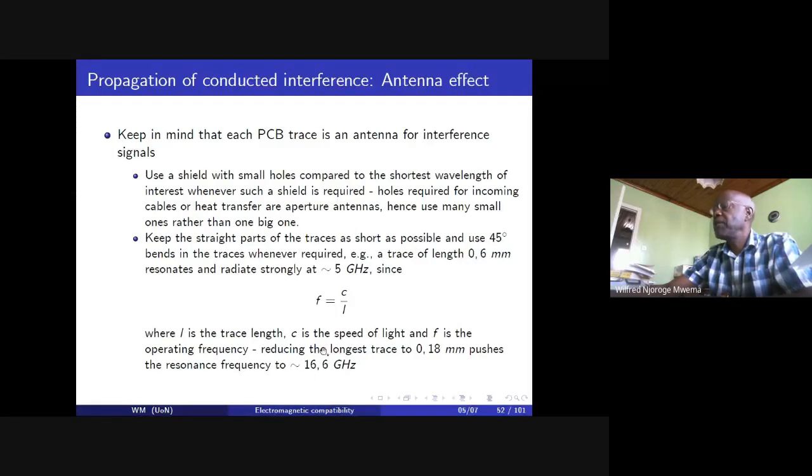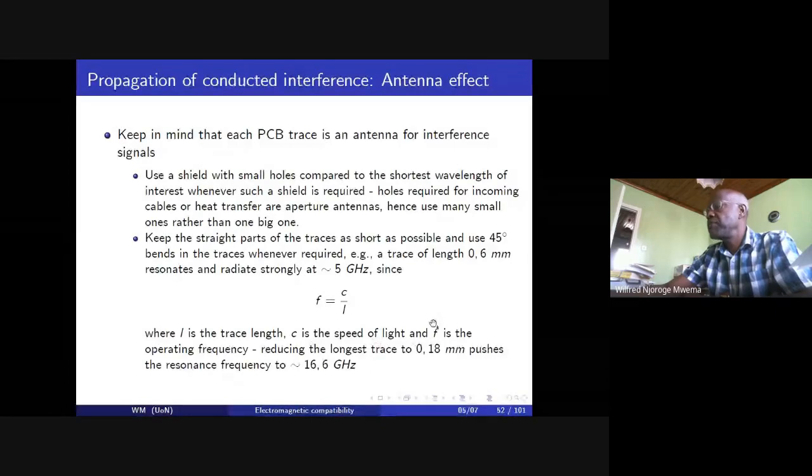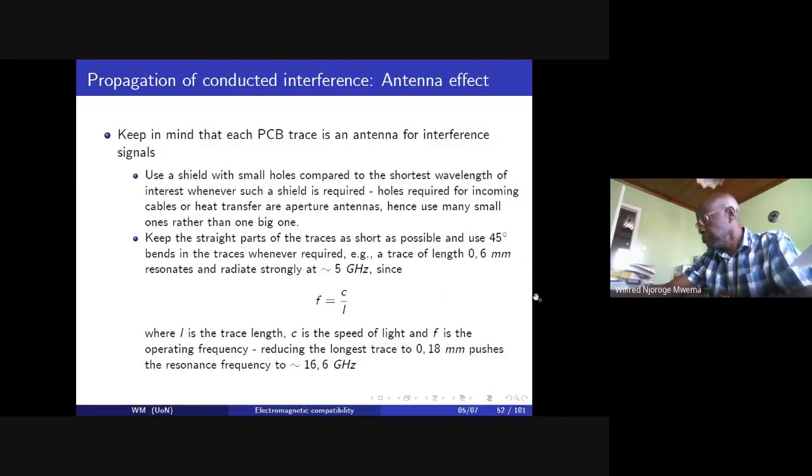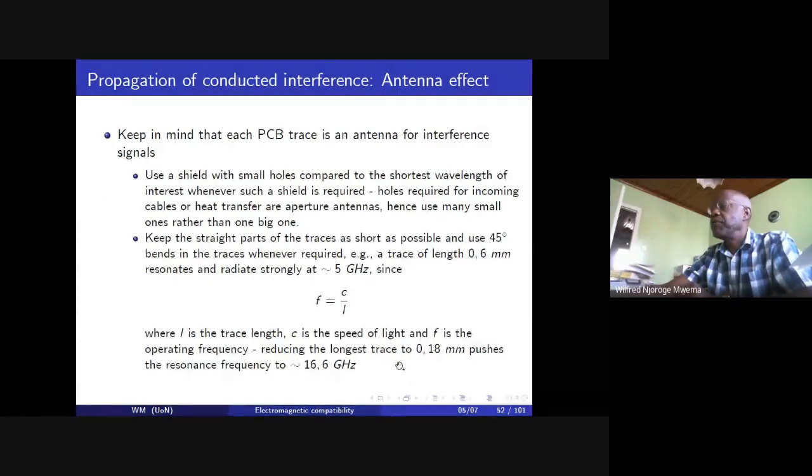With square waves having harmonics of one over the harmonic level squared, the power in that harmonic at 16.6 gigahertz for that clock will be very, very small indeed, and will be below the regulated level of power given by the standards themselves.